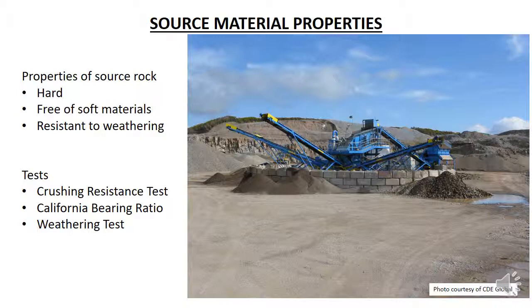This section also sets out the amount of testing required. For example, if the rock being quarried changes, then a new test needs to be done. However, if there is no change in the rock, then tests need to be taken on one sample for every 10,000 cubic meters of rock quarried.